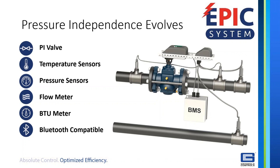And so if we can directly control the delta T, the temperature drop across the coil or the heat transfer equipment, if we can control that delta T, then we don't have to control the flow. And if we can optimize that delta T, then we can pump less water.